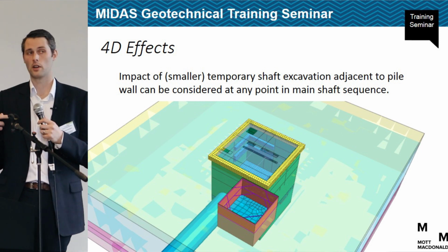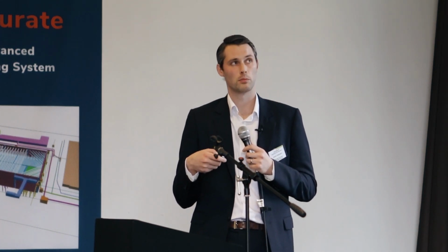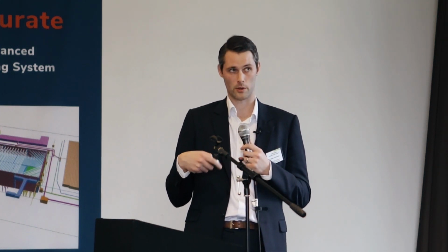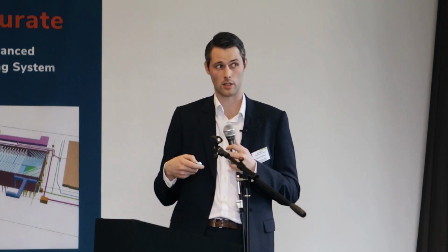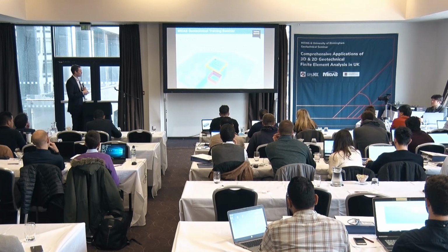So with Midas we're able to, one, model these 3D effects, but two, because currently there's uncertainty as to when this will go in, using the construction sequence modelling in Midas, we can drop this in at any point in our sequence. So if in 6 months' time the client says, actually, this is going in whilst we're doing the box, we can very efficiently start to look at the impacts that might have. So I think that's all from me.